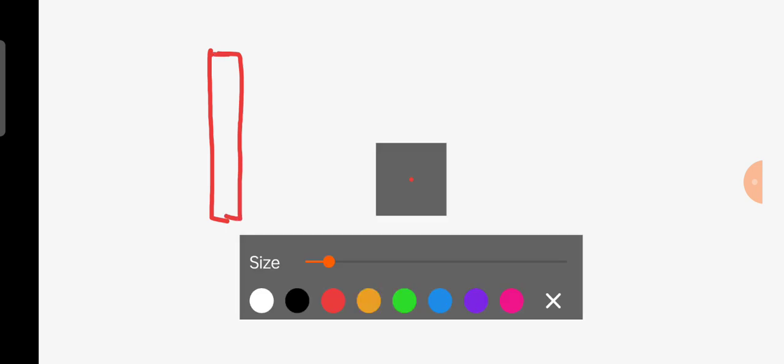When polysilicon crosses diffusion, or when diffusion crosses polysilicon, let us consider this is polysilicon. What is the color of polysilicon? Red, absolutely. Now it is a diffusion. Now will you please tell me, green color represents which diffusion? Absolutely, N diffusion. Now let us consider this one is an N transistor channel.